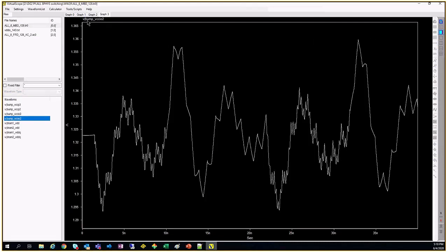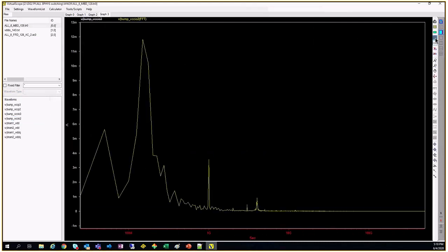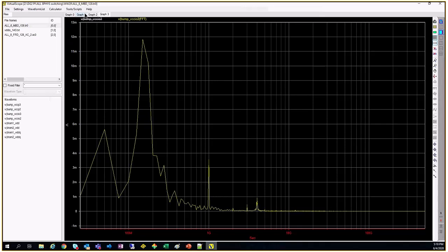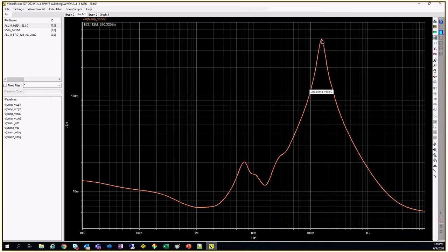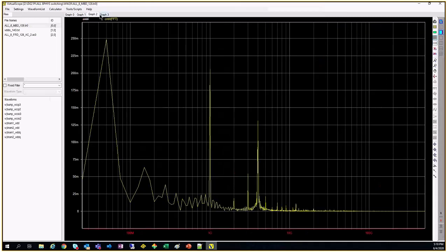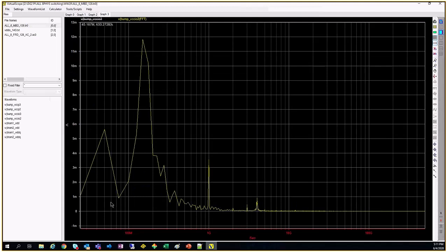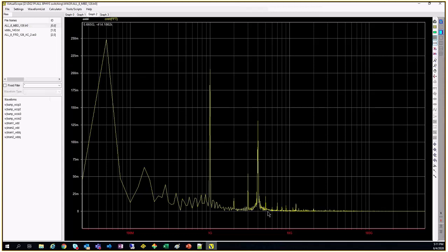So if you see here, my highest drop is seen after 100 mega. And why is that? Because after 100 mega only I'm getting my highest impedance. So obviously at this frequency, you will see most of my drop is at that time. And at lower frequencies, it is a little bit lower. Below 100 mega it is low. And after that also it reduces dramatically. Why? Because the current after that is also low. After 1 giga it's relatively less compared to, let's say, 100 mega.